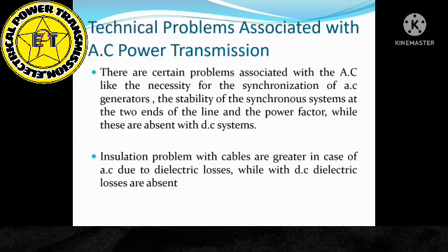Then again, there is the insulation problem with the cables. If you remember, the larger the operating voltage level, the greater the insulation issue. That's why I told you that if you think transmission of power is only feasible by increasing the transmission voltage, we are not right. When we increase the voltage, there will be insulation problems, and heating is a problem. So you must consider all these issues: insulator costs involved, stress on insulators.